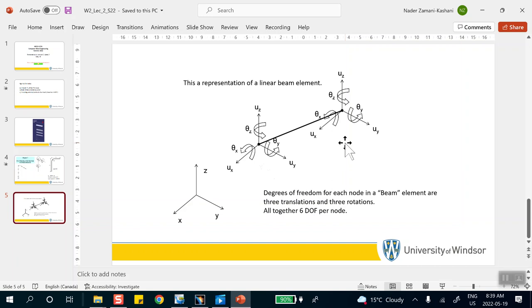And why did I say that? Because this is the same rule for beams, except that rotations become important too. The rule is very simple. If XZ is a plane of symmetry for a beam, things do not move in the Y direction, correct? Rotation is exactly the opposite. In other words, translation in Y is 0, rotation is free. The translations in X and Z are free, there it's fixed. Rotation is fixed. It's exactly the opposite. We'll come to that later.